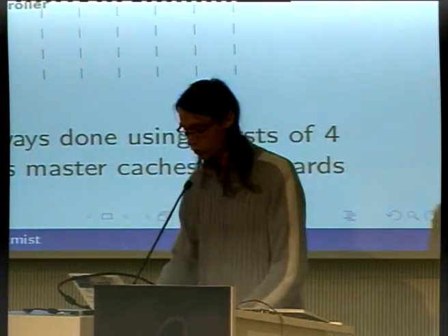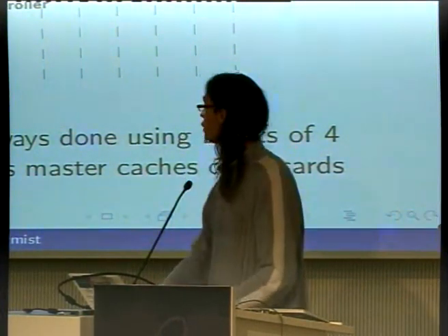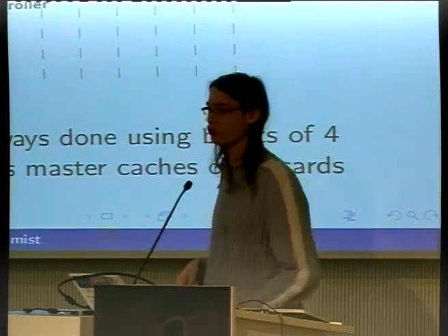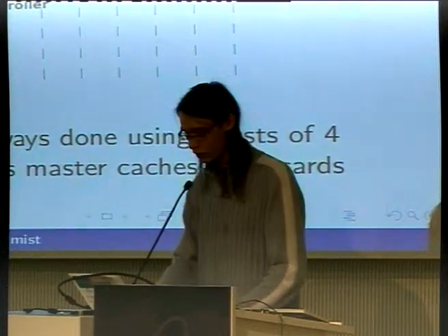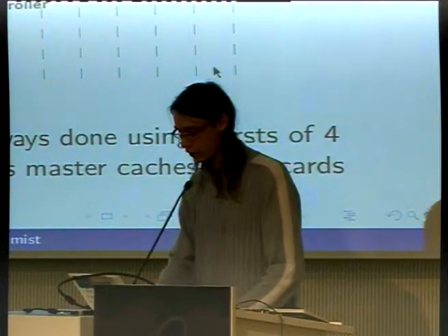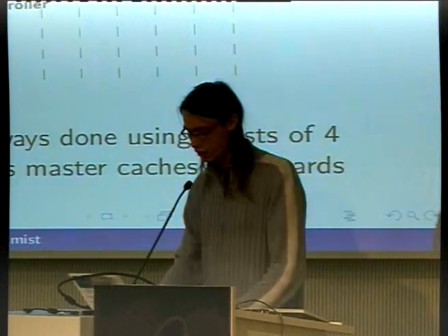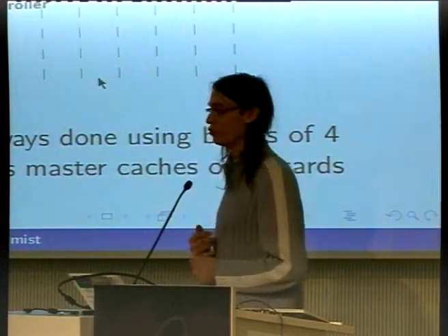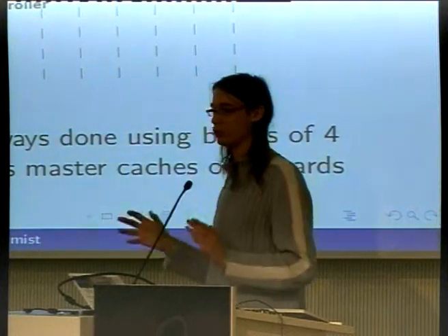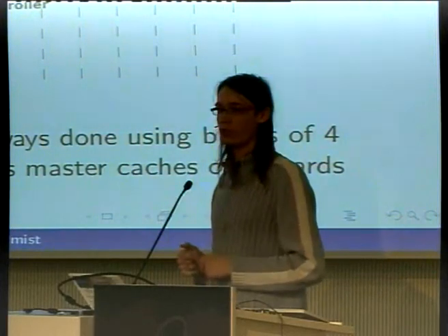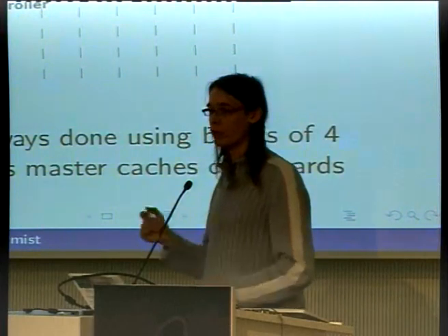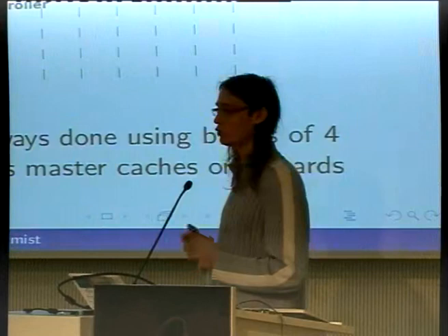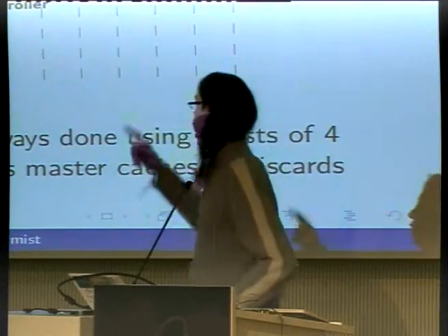And you can see that if you optimize the SDRAM controller, the memory access time will really shrink, and you can really use 100% of the bandwidth, because if you keep the figures that I gave, which is 3 gigabytes for a DDR200 chip, is when every slot is taken here. But to take every slot, you need to issue also a read command at every slot. And so you need to predict perfectly the address sequence that you put into the SDRAM. And on top of that, you have other problems like memory refresh, or sometimes you have to change rows in the DRAM array. But these are more technical points that I'm not going to cover today.